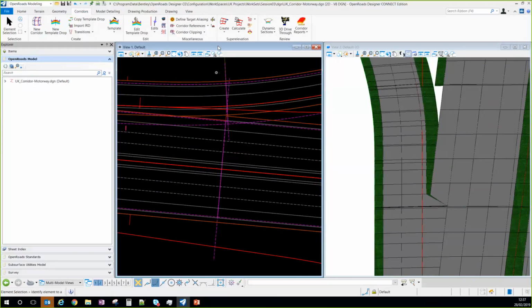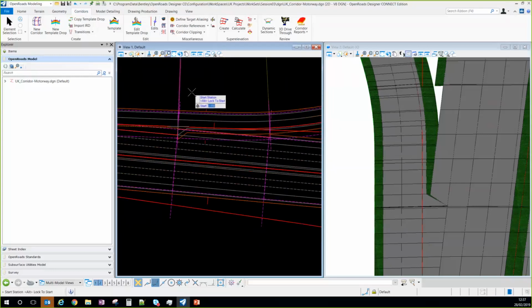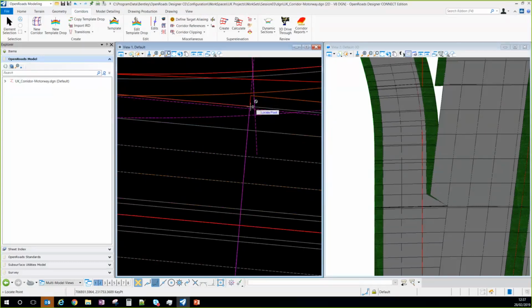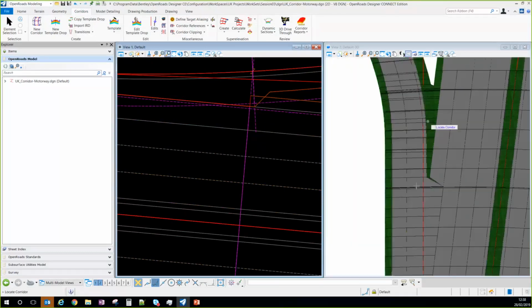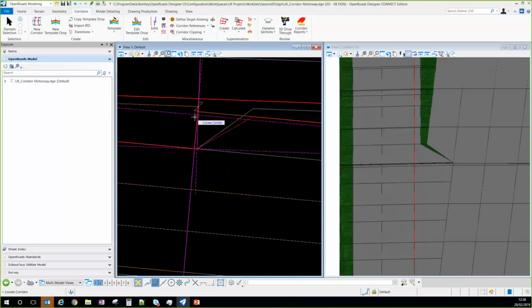And recreate it. So let's do it again. Select my corridor, the stations, that would be this one until this one. Verge, my points will be the verge. Both, linear geometry, hard shoulder, and this time it's okay. Now we can see that it's not really what we want, so what we can add is a key station here.